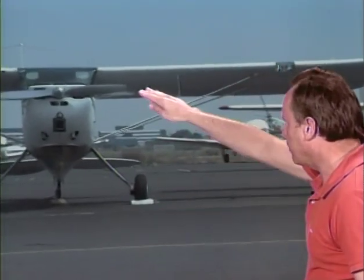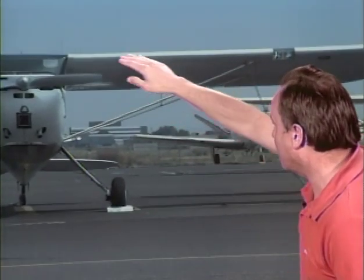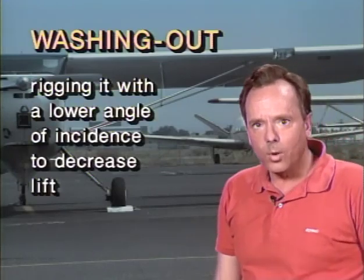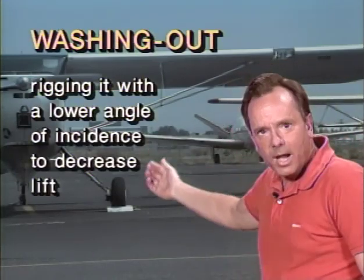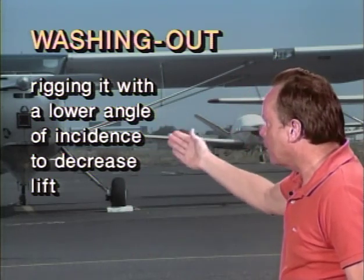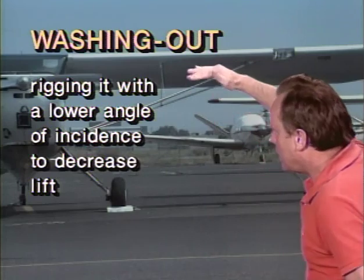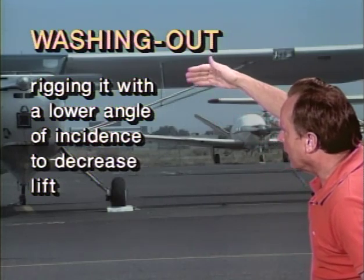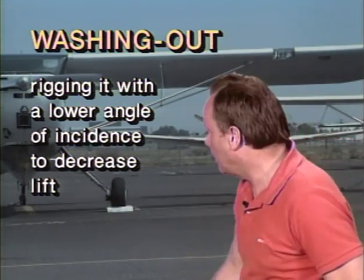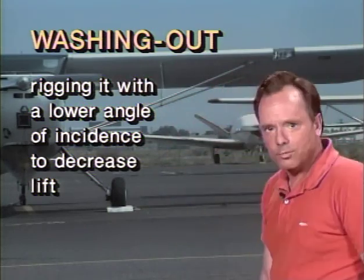We're talking about the angle of incidence of the wing all the way from the root to the wing tip. Washing out of a wing is done by rigging it with a lower angle of incidence to decrease lift. So if you change the angle of incidence of this wing so that you lower the angle of incidence to decrease lift, that's called washing out of the wing.